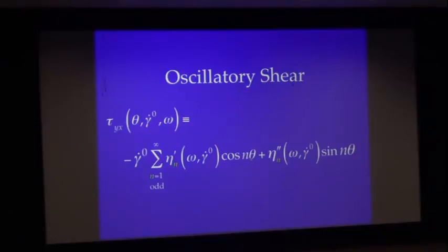If I draw an oscillograph here, if I take the left side of that equation and plot it against the shear rate, this is an idea that John Dealy had at McGill, then you'll see if that were a linear viscoelastic, if it were small amplitude, this would be an ellipse. But the complexities of the fluid distort it from the elliptical shape and give you a much more interesting shape. Those higher harmonics, 3 omega, 5 omega, are sculpting the shape of the stress response into this interesting shape.